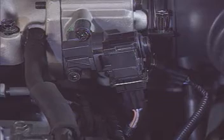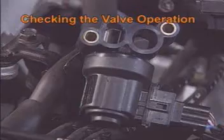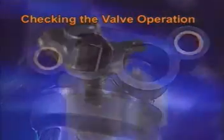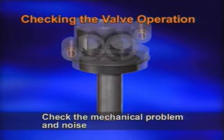Next is checking operation. Remove the idle speed actuator from the engine and operate the engine. Then check for valve operation as given duty percentage and any noise while operating. Through this, we can check the mechanical problem and noise of the idle speed actuator.